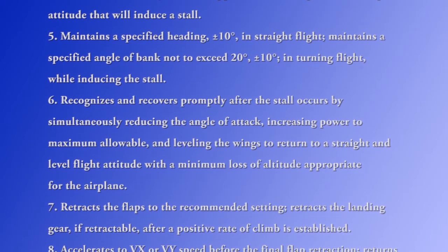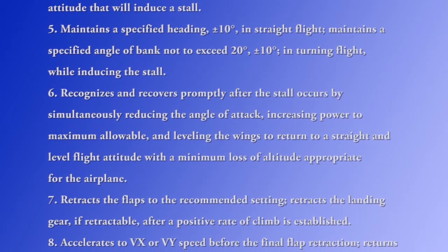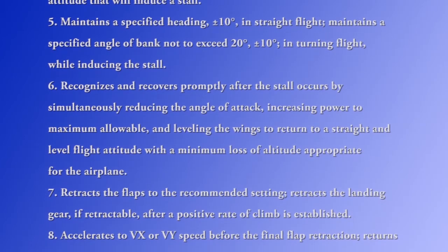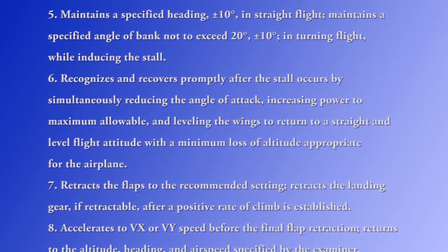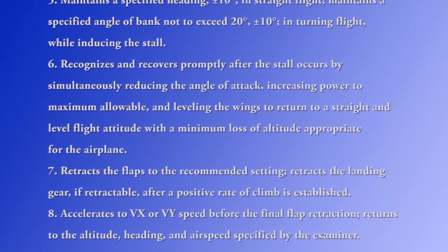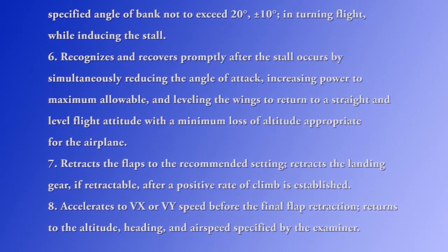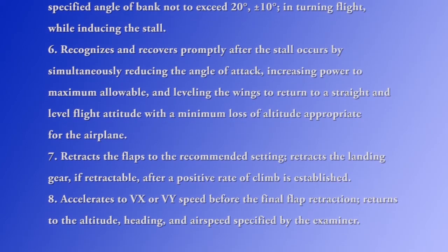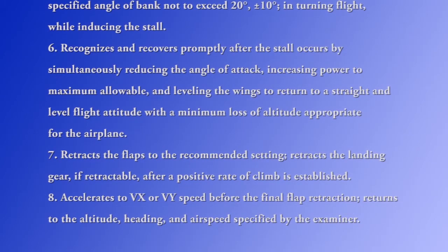Retracts the flaps to the recommended setting. Retracts the landing gear, if retractable, after a positive rate of climb is established. Accelerates to VX or VY speed before the final flap retraction. Returns to the altitude, heading, and airspeed specified by the examiner.